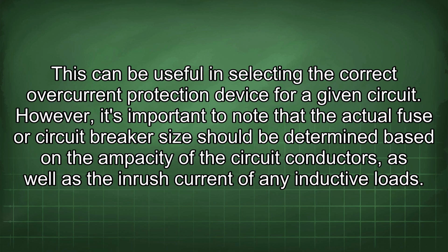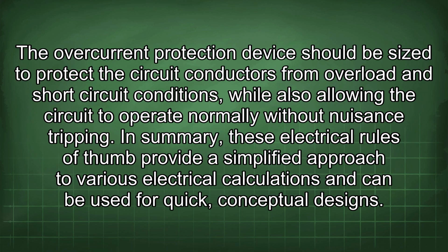However, it's important to note that the actual fuse or circuit breaker size should be determined based on the ampacity of the circuit conductors, as well as the inrush current of any inductive loads. The overcurrent protection device should be sized to protect the circuit conductors from overload and short circuit conditions, while also allowing the circuit to operate normally without nuisance tripping.